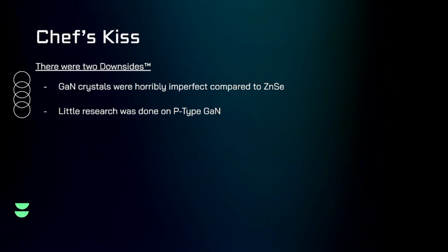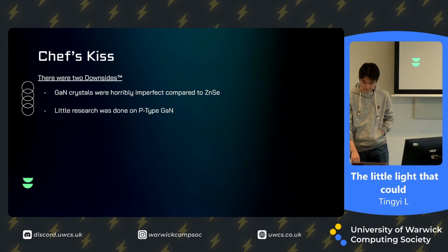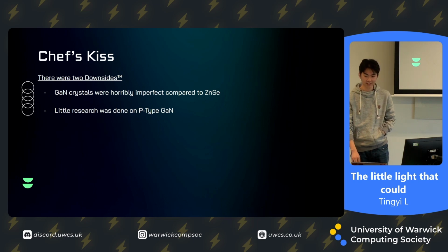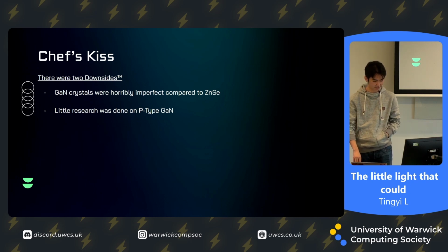There was another thing of research on p-type GaN, and p-type GaN can be made by doping with magnesium, but it was ineffective as a p-type material. We'll talk about this a little bit later because it's really funny about how he kind of just did it. But on the question of n-type GaN, I believe they doped with silicon to add that extra electron, and basically silicon doping was very well researched as a method of making n-type materials at that point.